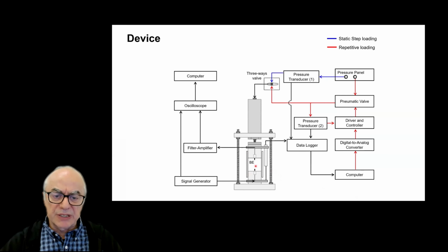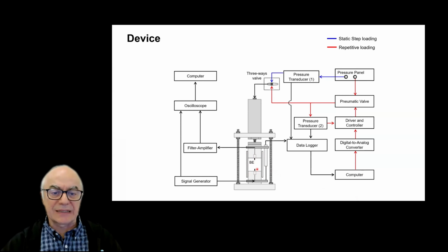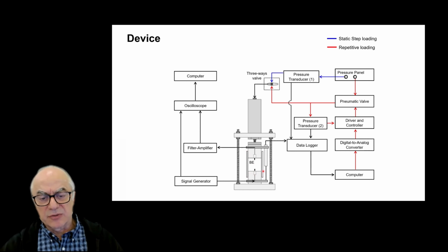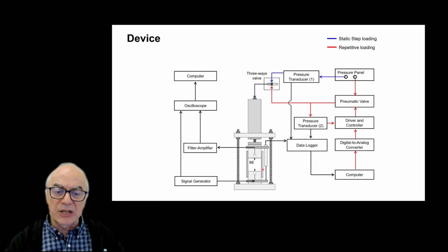This is a floating ring oedometer. This is where the specimen is contained. And we mount bender elements so we can also monitor the evolution of the small strain shear stiffness. The advantage of using a floating oedometer cell is that we minimize the side friction very significantly, as you may remember from previous analysis. Otherwise, there is an exponential decrease in the vertical stress.